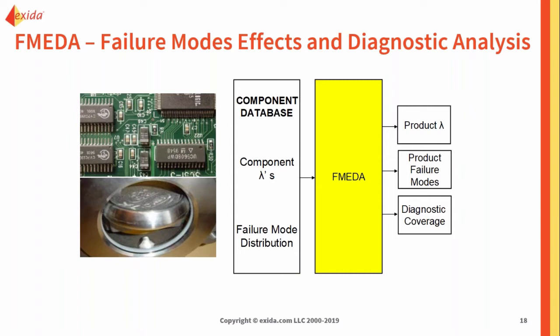This is because a failure mode might be dangerous in one application but is safe in another application. If you think of a valve that opens on trip or closes on trip, a failure of being stuck open or stuck closed or not able to open or shut could be safe or dangerous in the different application or operations.